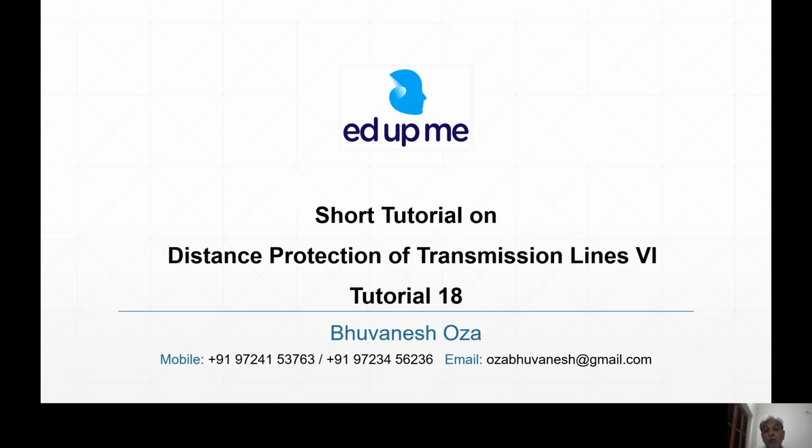Underreach of mho relay is less than impedance relay. Underreach of reactance relay is nil. It is immune to fault resistance. But mho relay can incorporate some fault resistance. But the best relay is the quadrilateral relay about which we were talking.